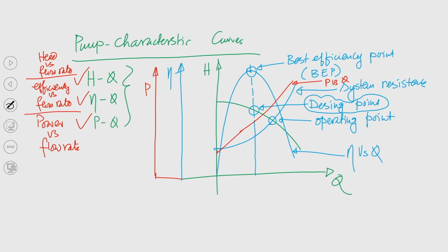We also need to know the requirement of power, because when we calculate efficiency, which is essentially the overall efficiency, we need to know the input power to the pump, and out of that input power what is the output power in terms of head and discharge. So, we have also superimposed that curve in this plane. Fine. What is next important?